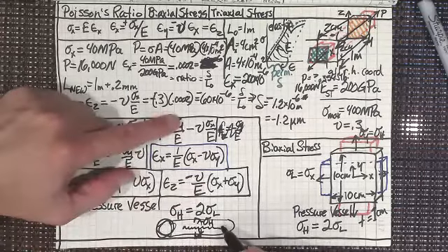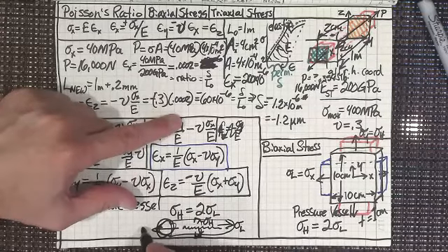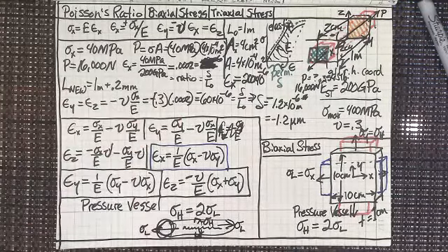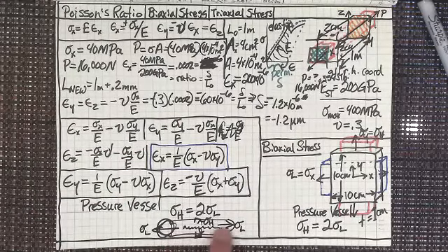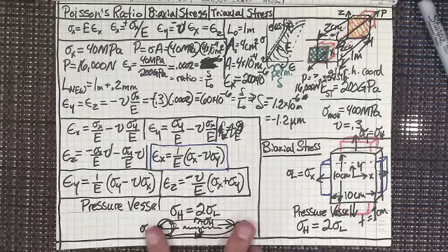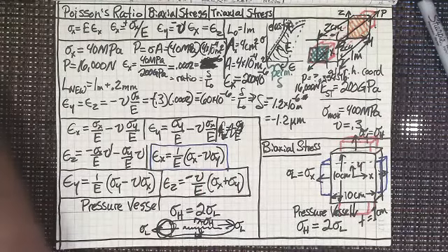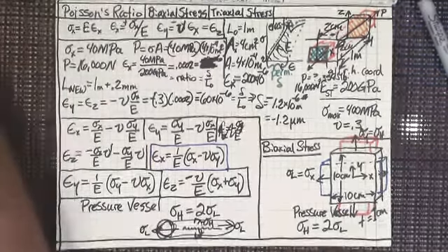Now I've also got a longitudinal stress, which is pulling in this direction, right? Any pressure vessel never breaks this way. It never blows up and separates that way. It always rips with a seam down the side. Every pressure vessel has that built in, that it'll rip with a seam down the side rather than blowing up. I've got a great story to tell you about that when we get there too. All right, that's it for this lecture, and see you at the next lecture.